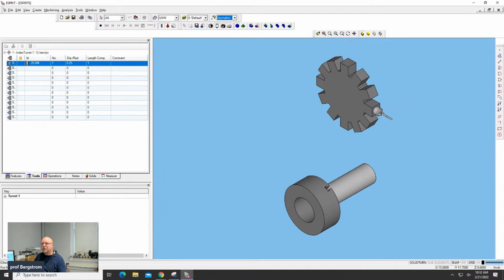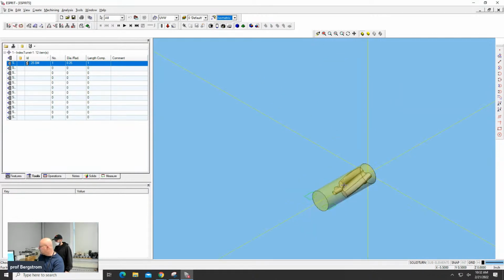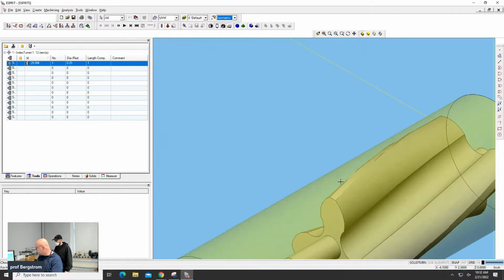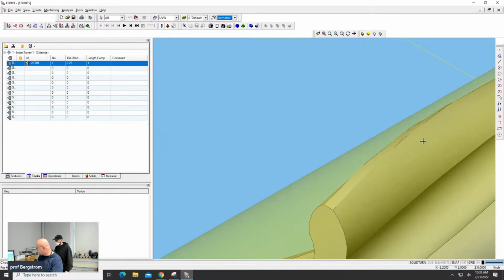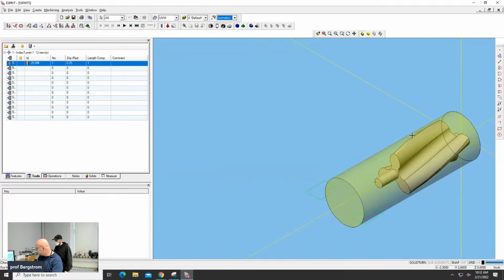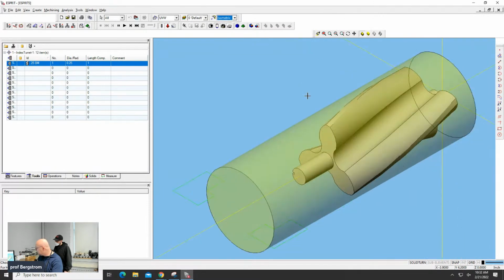No, but I'm serious. I want to know how to program this toolpath now. Oh, I think I'm doing wrap contouring. That's what I thought too. So how do we make the feature? It's going to be a chain along one of these edges, like the top surface edge. Yeah, I probably would. The only thing that's going to be weird about that one though is it's a surface. Don't we have to make the drive chain thing? Yeah, you probably will.